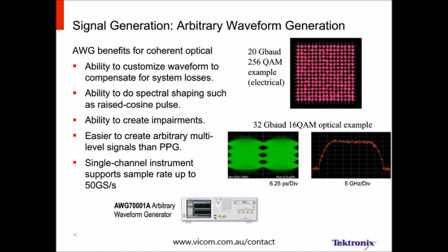So it basically gives you an idea: okay, the unit may have more bits than that. In our case, this is a 10-bit D to A converter, so the unit has more bits than that. But what can you expect to use practically when you take into consideration the noise and the distortion? However, the ENOB is usually quoted in a certain bandwidth. If you use less bandwidth than that, you're letting in less noise, you're letting in less of the harmonic distortion, and so the ENOB actually gets better as you low pass filter.